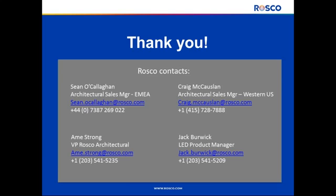Okay, other questions? There's one here on IP: how do you seal the waterproof tape if field cut? If you want to customize or have custom lengths of the IP65 tape, we recommend you feed that information to Rosco, and then we can provide it cut to length. But where you might need to do some field cutting, it can be resealed using silicone sealant material, and we can provide appropriate instructions on how that should be done.